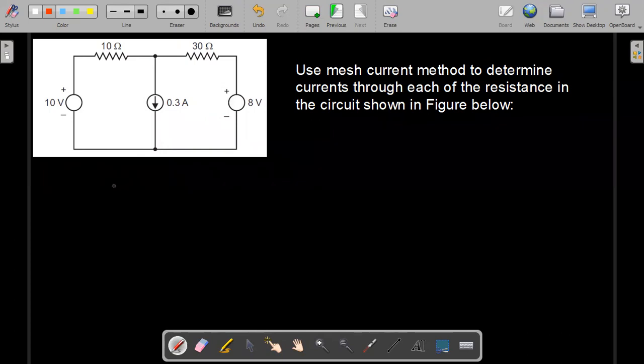The first thing that we do in such type of networks is we assume some voltage across this particular current source. So let us say this is a node A and this is B, this is node C for example, and this is node D for example. Now we will assume some voltage across this current source. So let us say the voltage is Vx, right? So the voltage here is Vx, and rest of the things we will do in the similar manner as we did with the circuit where we did not have the super mesh case, right?